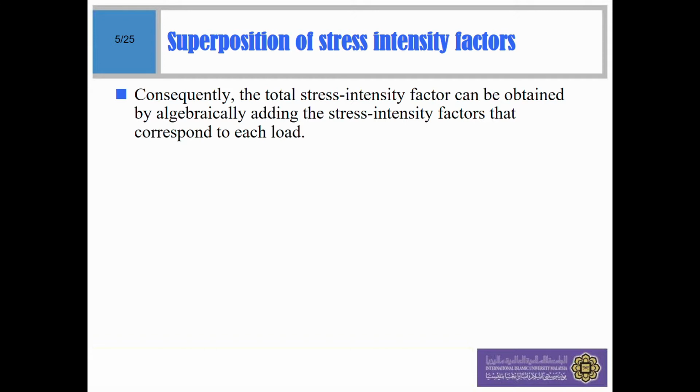So if the question is giving you one complex crack geometry, in which you cannot determine that by one single calculation, you have to separate that and then combine each stress intensity factor.